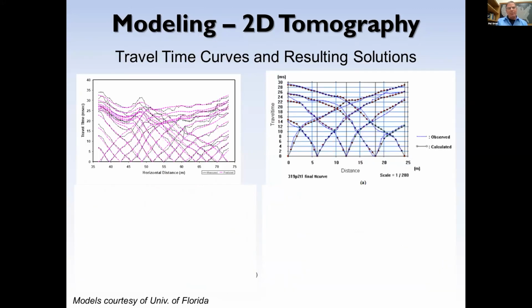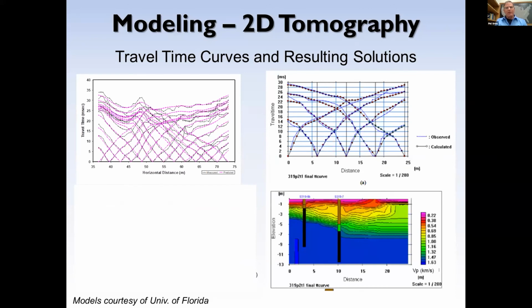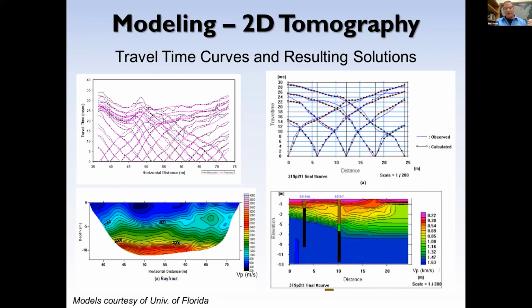So I just used one example of looking at two travel time curves that I shared earlier about how these work. Just from the travel time curves, experienced folks like myself or Jeff or anyone else on this call, Nolan, we look at those and right away we can tell something like on the right is probably a pretty simple 2-3 layer case. We've got some soft soils up top in red, an intermediate layer, and a dipping velocity layer at depth shown as blue. Whereas the left one, those are pretty complicated looking travel times. But they might be due to surface relief or bedrock relief, meaning topography or relief on the bedrock. It ends up in this case, because this is from Florida, a flat lying surface, it's relief on the bedrock.